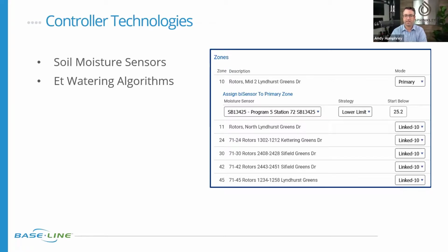So it's really that, stop or pause based on rate, and then either resume or not resume based on accumulation or effective rainfall. And the only place you can measure effective rainfall is in the root zone. It doesn't matter what landed in the catchment device. It's how did it affect the root zone? Yeah. Best of both worlds then. Yep. Beautiful. Very cool.